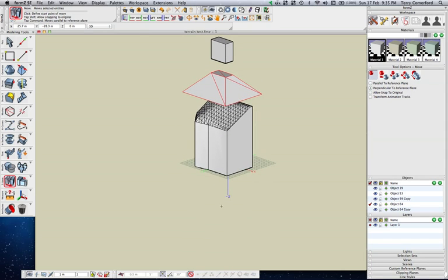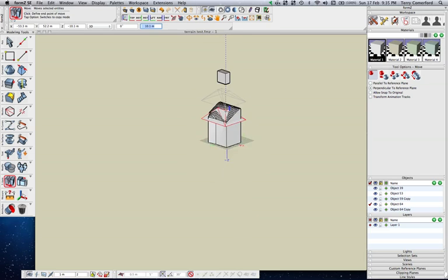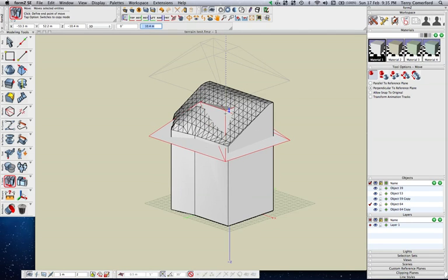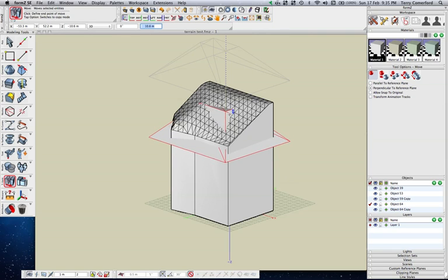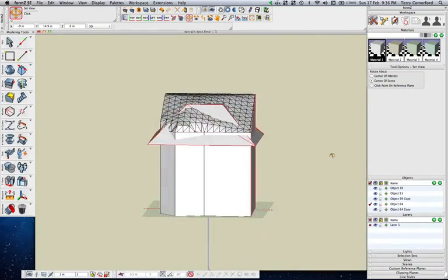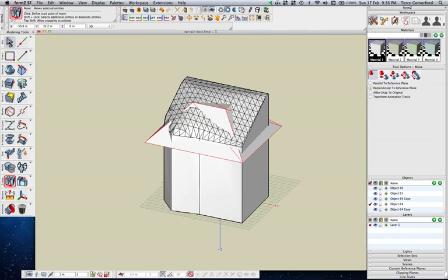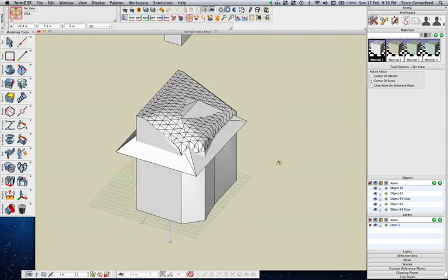So I can now click and drag that object down into my topography until it starts to take shape of the embankment shape that I want to use. So say I wanted to do something, and you can see you can change the height. You can see how you can change the height and get an idea of how much fill you're going to have to move into this site to create those slopes. So if I go to some sort of point like that, that looks like a reasonable sort of arrangement. Click there. I've got that embankment being made.